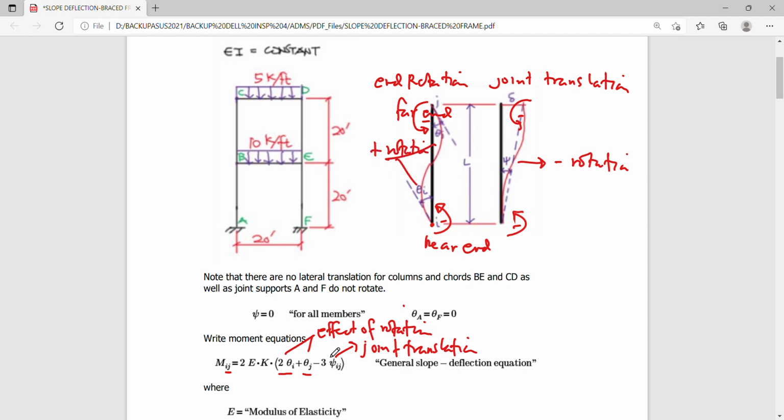That's why you can see here a plus, plus, minus sign. So when we're talking of rotations here, we are talking of the chord rotation, upon which we connect the two ends of the deformed configuration of your member to represent a chord. And since this is oppositely directed to that of the rotation at the ends, this is negative in terms of sign.